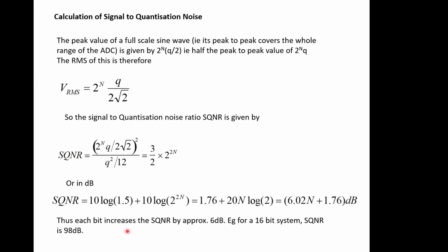People try and go higher, but there's not a lot of point really, because the noise in this system is so low that it's going to be dwarfed by any analog noise that you've got in your system, which is much more difficult to get rid of at low levels.